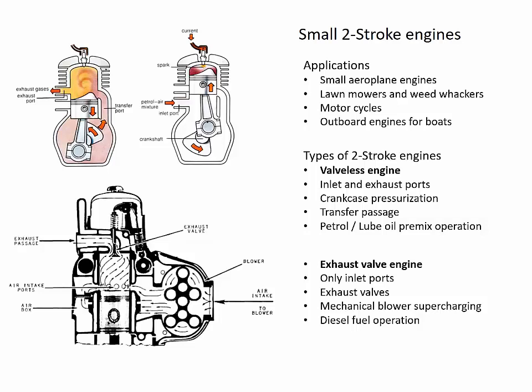So to wrap it up, the upper engine is a petrol engine, spark ignition, crankcase pressurization, no valves. The lower picture is a diesel engine. It is supercharged. It is having only inlet ports and exhaust valves.